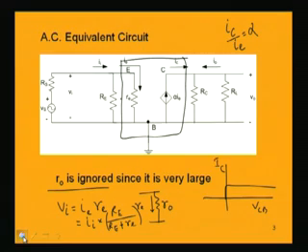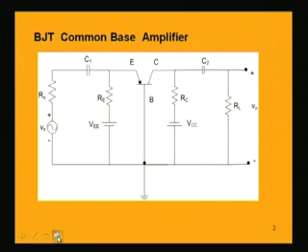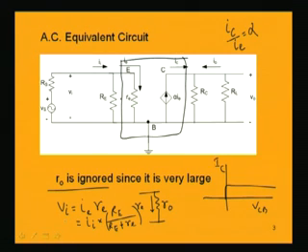That is very evident if we look from this input terminal into the transistor input circuit. We are having two resistances in parallel, one point is connected to the emitter, the other point is ground. So, these two are parallel resistances. We have this parallel combination as the input impedance, and mind it, although I am using the term impedance, basically all are resistances.